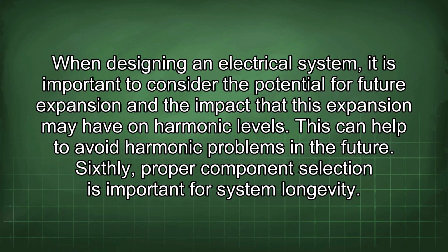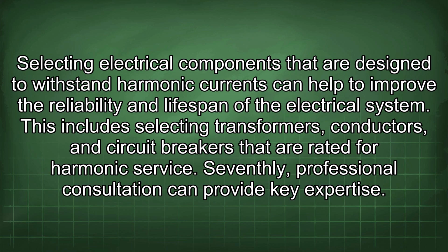Sixthly, proper component selection is important for system longevity. Selecting electrical components that are designed to withstand harmonic currents can help to improve the reliability and lifespan of the electrical system. This includes selecting transformers, conductors, and circuit breakers that are rated for harmonic service.